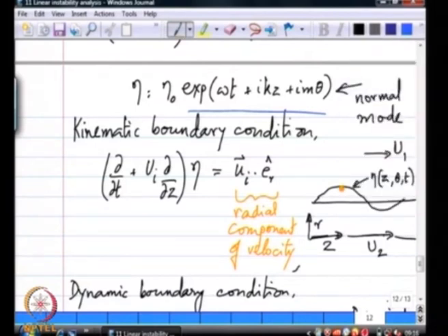If I take a material point that is on the liquid jet surface, this material point inside the liquid surface has a radial velocity u r, which is given by the perturbation field ui dotted with e r. So, the magnitude of this radial velocity u r is given by ui dotted with this radial unit vector in the radial direction e r. This u r is the Eulerian velocity inside the jet. That is essentially what we find.